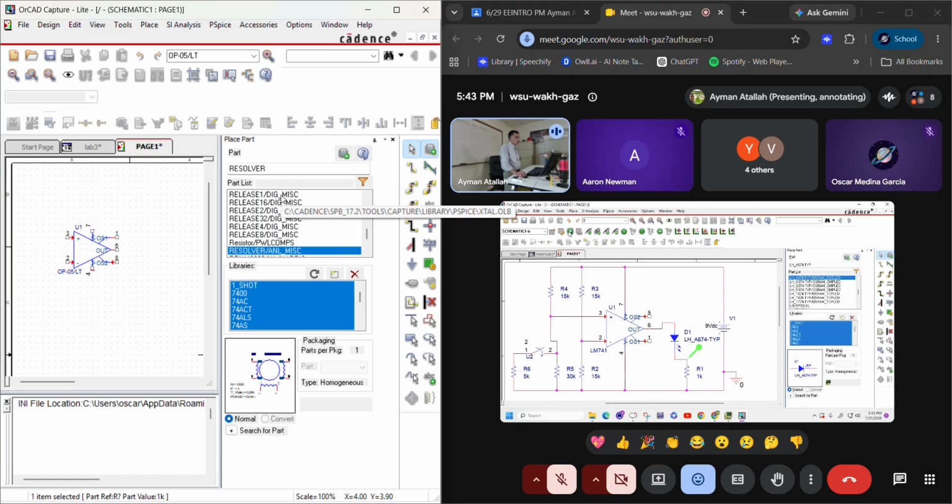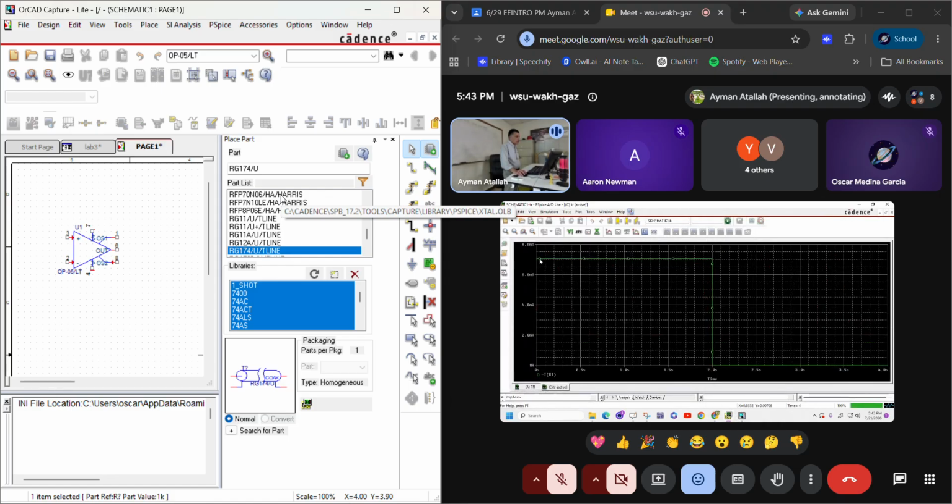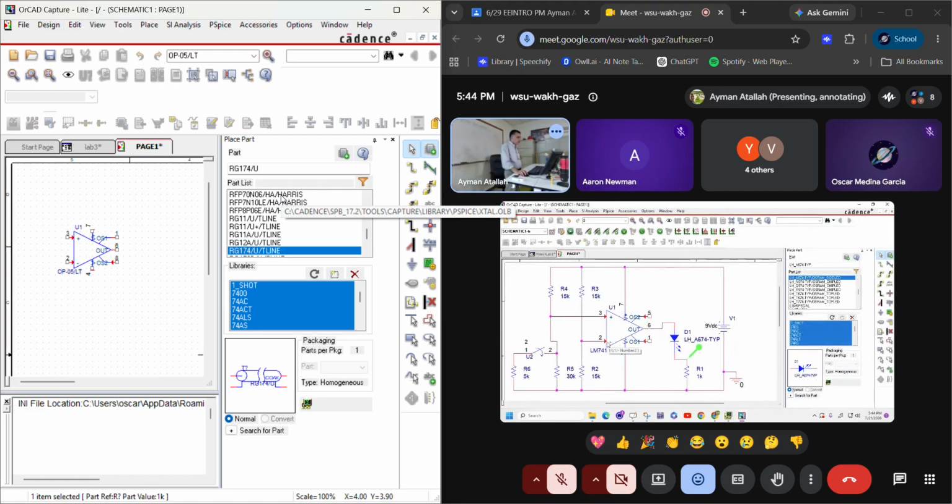So you're supposed to get this as the output here, not this one. Okay. So you get current as the beginning from 0 to 2 seconds. There is a current through the diode, so the diode will lit. After 2 seconds, the diode will turn off. Mine's the opposite way around. Okay. The opposite way around, how do you connect this to this one and this to this? Because it depends how you connect these 2 points and the values you choose here.